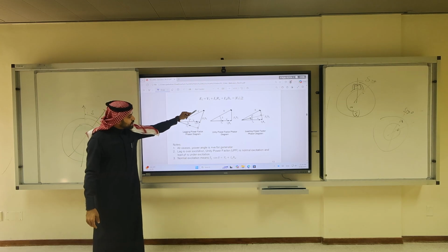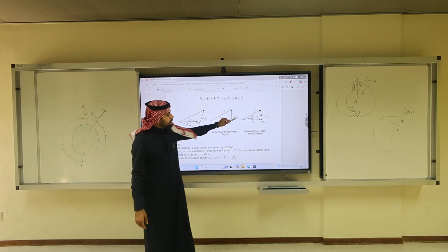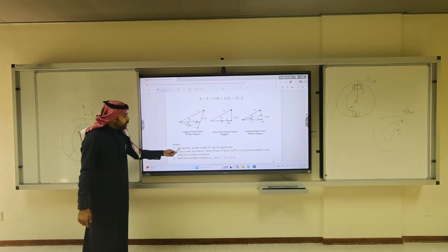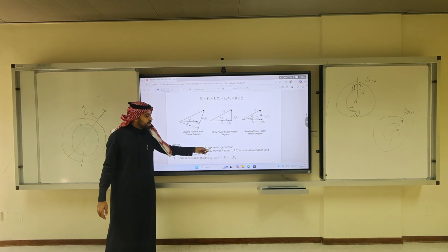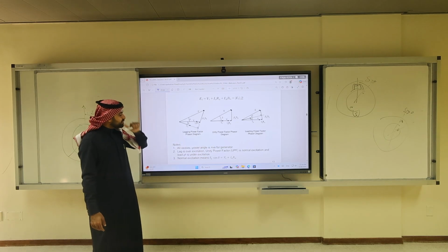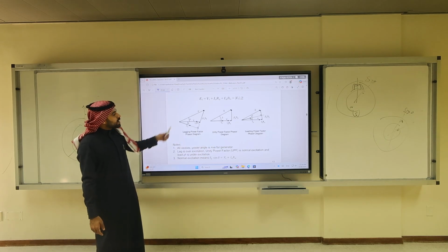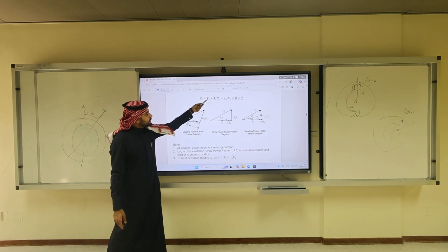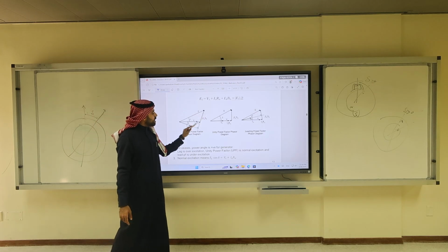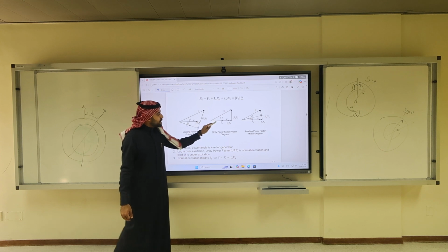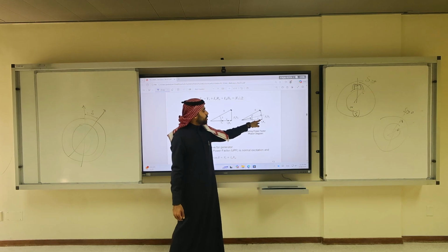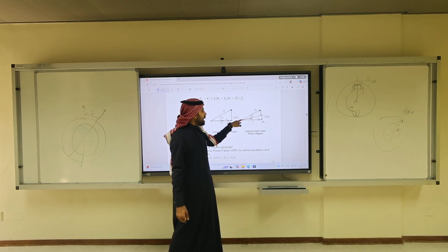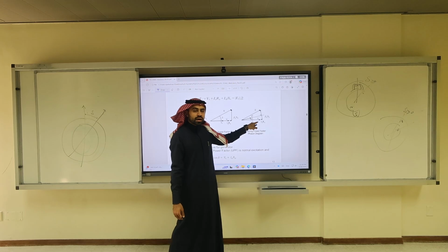Delta is the angle between E and V. In all cases, for the synchronous generator, torque angle or power angle is positive. That's one thing. Another thing I need to know is to get the E, I need to get Vt plus IARA. This small arrow is IARA. Note that we just scale the IA with the number RA. Usually RA is a small number, so that's why the arrow is smaller.